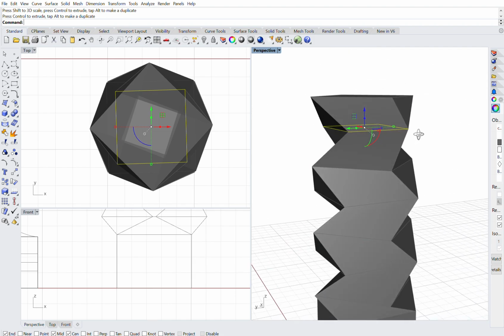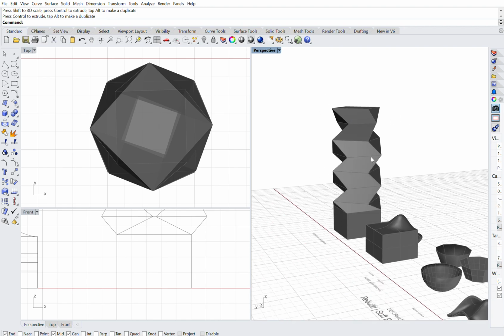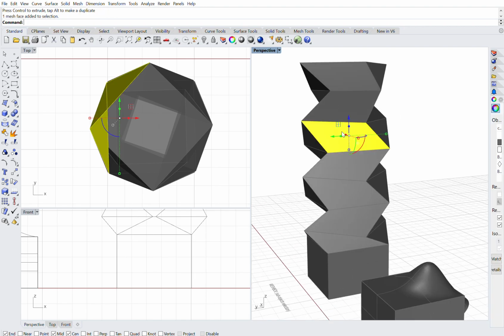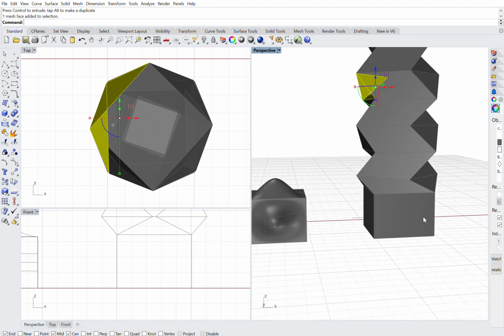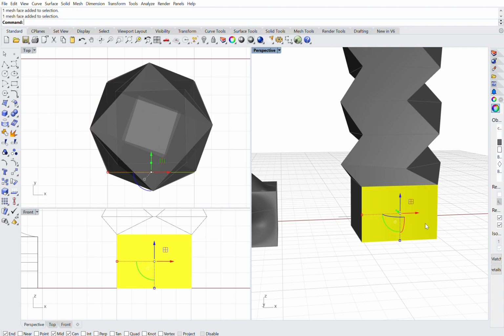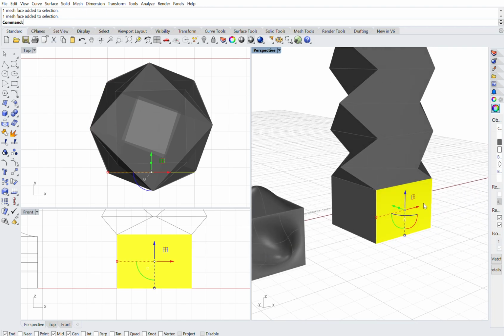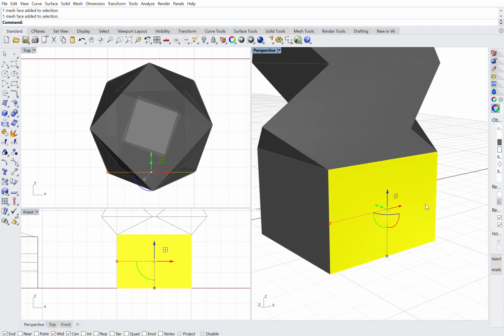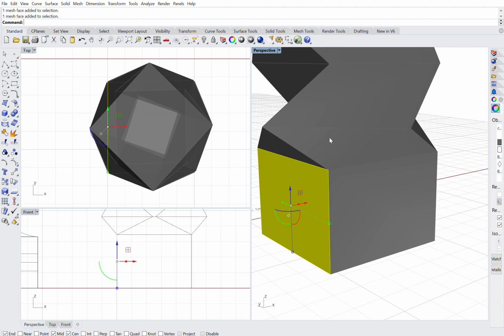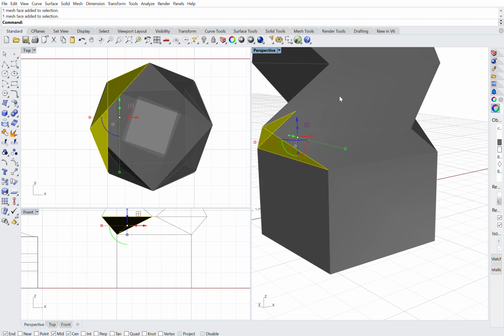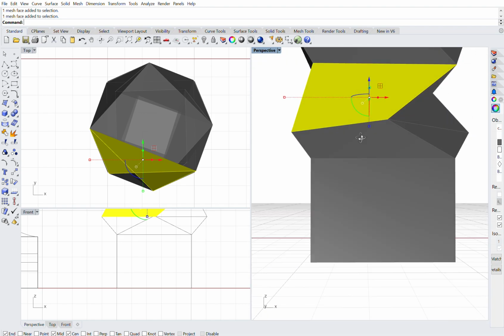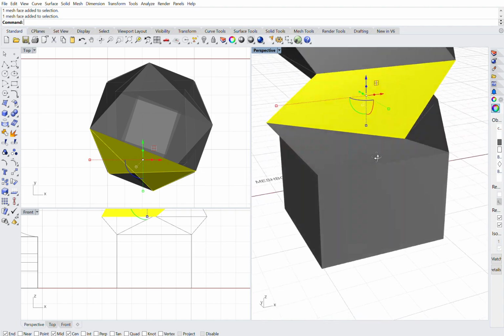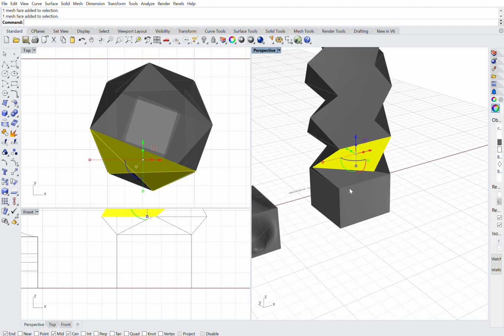Right. So what it's done is technically, as you've rotated it, each polygon of this structure is no longer planar. So when we initially created this mesh, this initial box down below is planar, which means you'll be able to develop it and laser cut this piece and that and so forth. But when you rotated it, it's no longer flat, so the surfaces are now curvilinear, and you won't be able to use laser cutting for this.